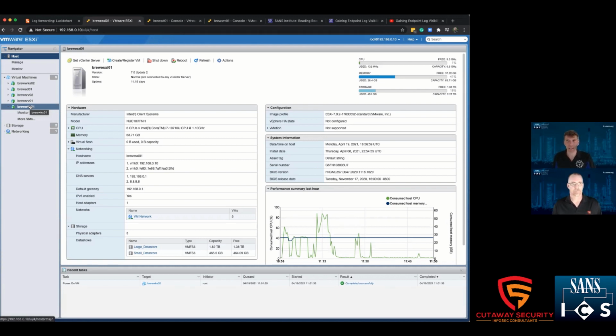And definitely with this kind of technology, I always recommend that you deploy small, even in your plant environments. Deploy small and deploy to your less critical systems. And then once you've got all the kinks worked out with the settings and so forth, then you can begin to deploy maybe to your Purdue level 3. And then from there, focus deployments down and down and down until you get complete coverage.